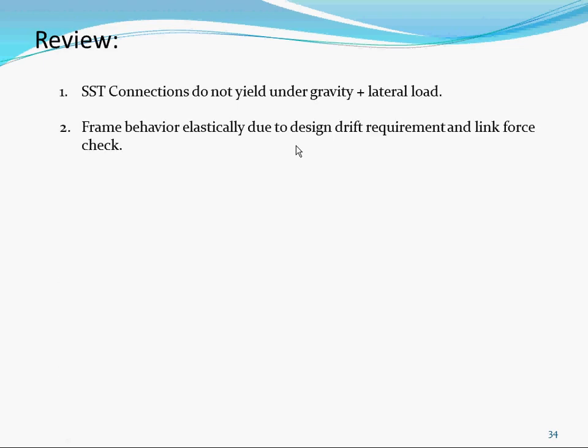Okay, so review. SST connections do not yield under gravity and lateral, and that's what we're trying to do. The frame behaves elastically. Include the wind load. When we say lateral, it's typically either wind or seismic. When you look at a load combination, and I'll go over that later, you don't combine wind and seismic. You only do one or the other.